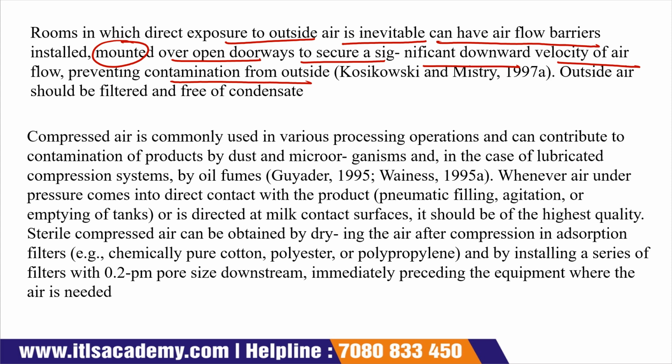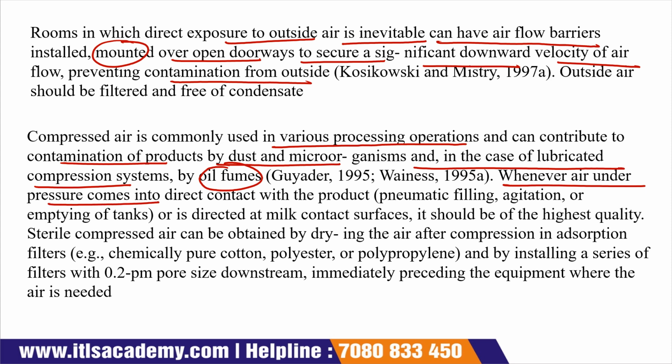Then compressed air is commonly used in various processing operations, and it can contribute to contamination of the product by dust and microorganisms, and in the case of lubricated compression systems, by oil fumes. Whenever air under pressure comes into direct contact with the product or is directed at a milk contact surface, it should be of the highest quality.